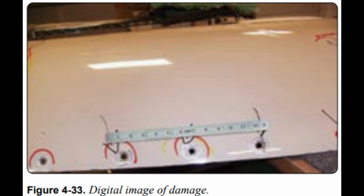To provide information about the extent of the damage, a measurement scale or other object, such as a coin, can be placed near the area of concern before the picture is taken. Also, within the text of the email, the technician should state the exact location of the damage, reference to fuselage station, wing station, and so forth.